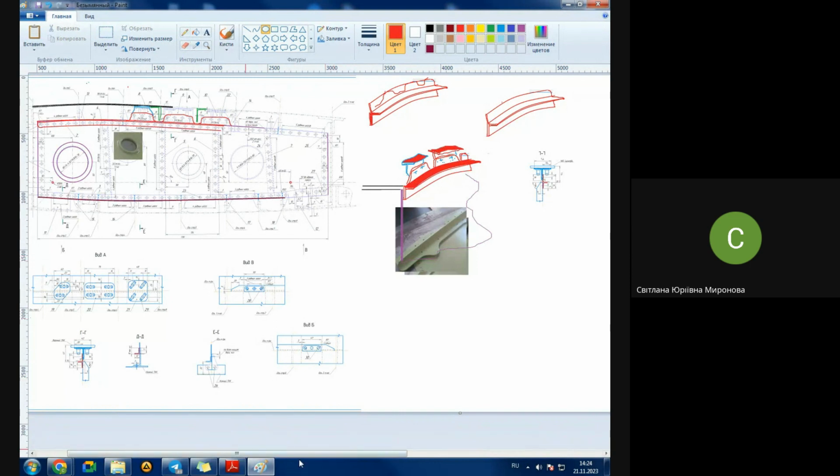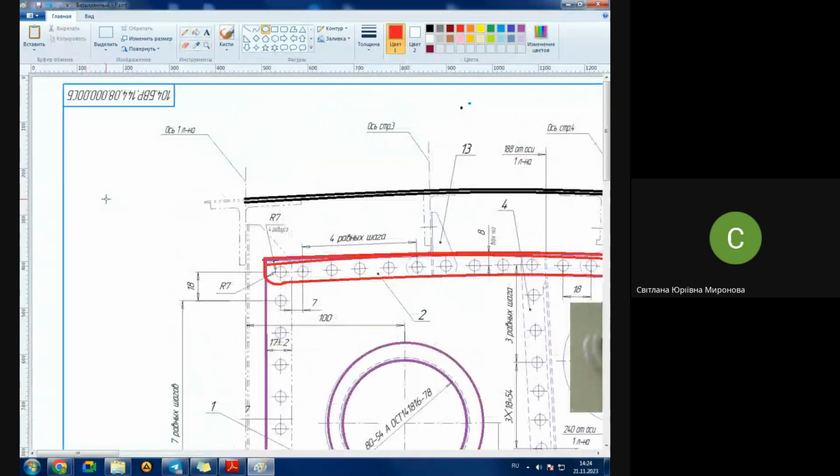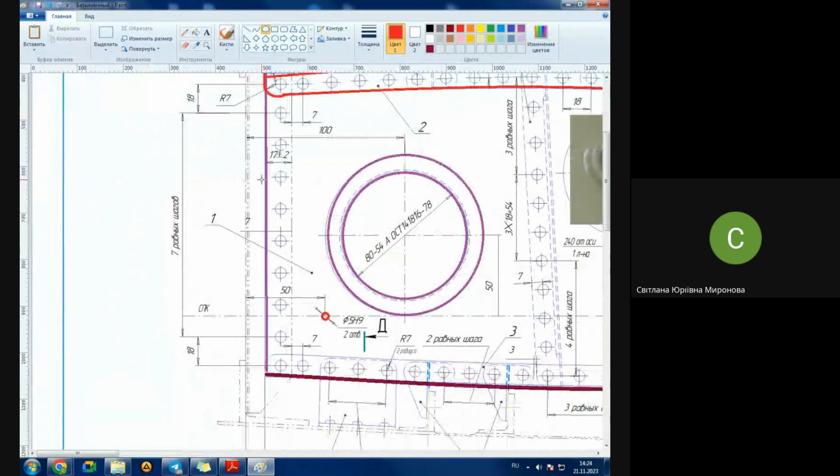Look, there are special holes which are manufactured with very high accuracy, so-called coordinate fixing holes. Their coordinates are given with respect to the main airplane bases, in this case with respect to the first span axis. I spotted not those holes even, but the dimensions of their coordinates. Normally these sizes are given in a step of 50 millimeters, maybe with some changes of code, but usually in a grid of 50 millimeters.